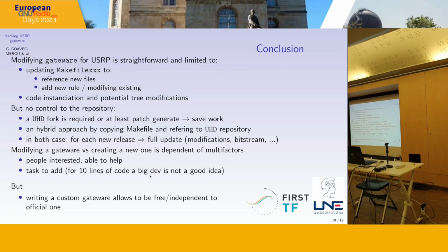And so the point of introducing this 55AA that you saw was to see how long it takes between the trigger of a PPS from the input GPS and the output of this corrupted stream, and so how much delay we have between the corrupted signal and the correlation peak output. That was actually the reason for introducing this corruption of the data stream, because it will hardly affect your correlation. If you just change one sample out of a 1023 correlation, it's not going to change the output of the correlation, but it allows you to identify the time delay.